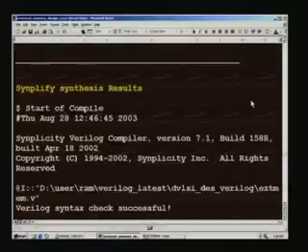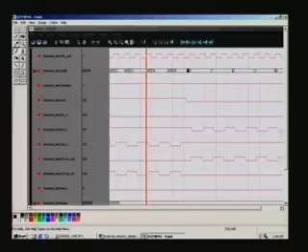So, we have one more waveform towards the end. So, that is when it is complete. So, the next address will switch over. For example, earlier it was high, and this is the second block as such, and when it touches the highest value here, RW is again made low, meaning thereby it is taken to write here, and with this we have done not only a write but also followed by a read.